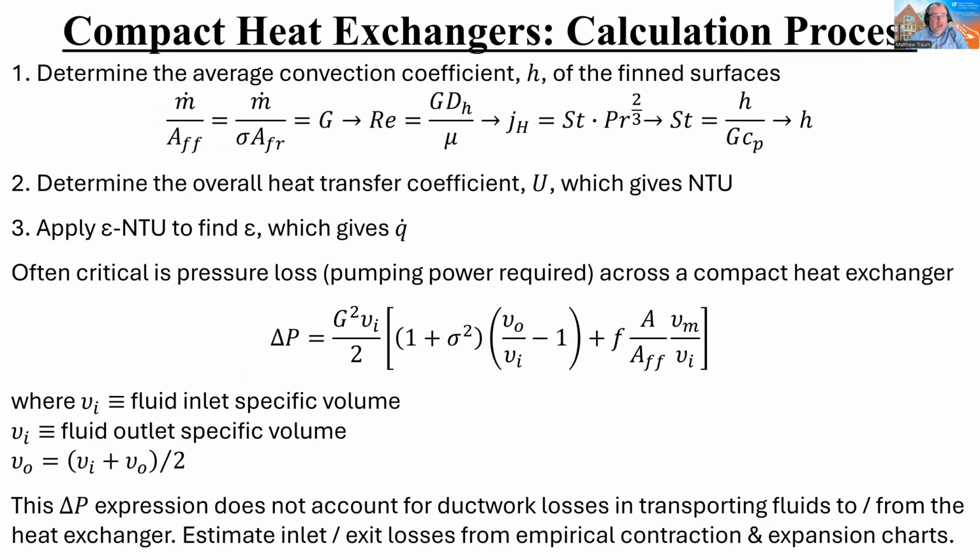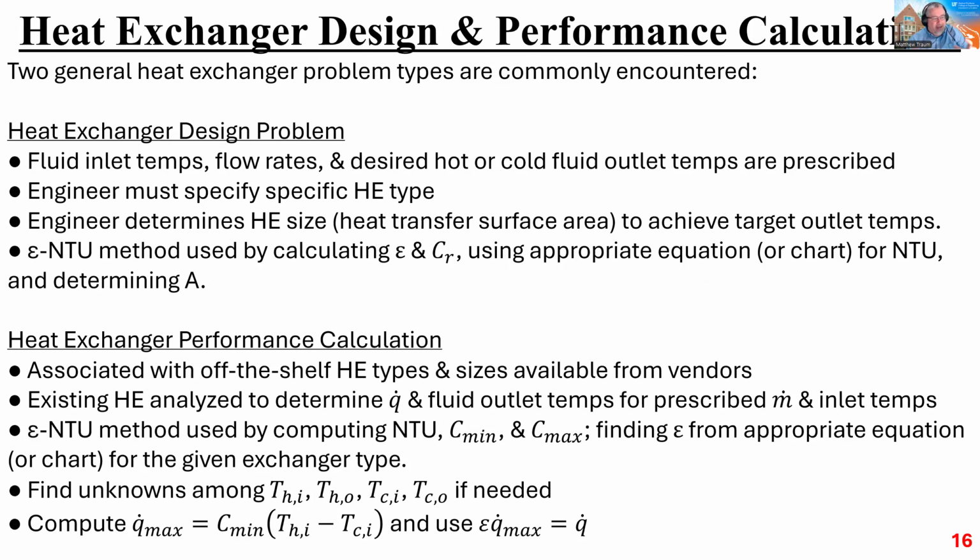In summary, heat exchanger design and performance calculations. There are two general heat exchanger problems that engineers in practice commonly encounter. The first is the heat exchanger design problem. So this is a situation where everything is known about the fluid inlet temperatures, the flow rates, and the desired outlet temperatures, right?